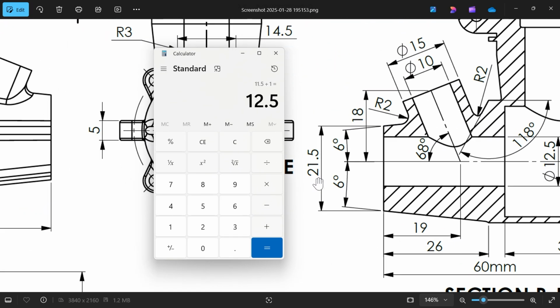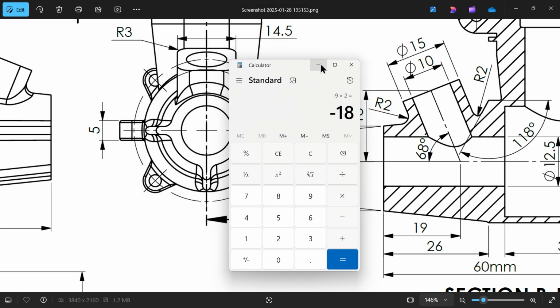Okay. Now what else can we do? Come here. Look, this half portion we calculated 12.5. This is complicated. You must listen. This half portion we calculated from the top view or detail view is 12.5. So minus 21.5, because this detailed section view includes the rib. Now this upper portion is 9. This is going to be the radius for this center line. 9 into 2, 18. So this is going to be the diameter excluding the rib, because the rib we are going to add later. 18. Fine.